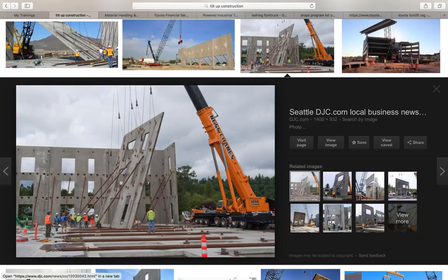Bend down projecting nails. A lot of times you'll see, especially with forming equipment or materials being pulled off, either pull the nails or the screws out, or at least bend them down or break them off, or whatever needs to be done to keep everybody safe, right? When carrying any types of bars with a partner, we need to make sure that the load's balanced as much as possible. We need to stay alert. With concrete buggies, I'm going to show you a couple of them. I think there's some on the next page, and I'll also show you on the internet if necessary. Never drop hoisted bundles or carried bars onto the form.